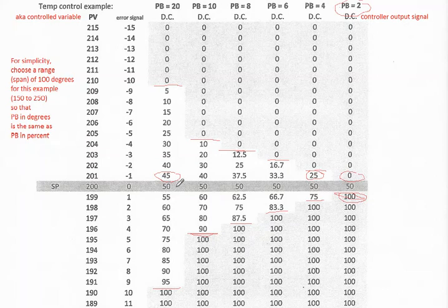We did talk about having that as another topic. You would need some flexibility there to make sure that the controller output signal matches what it would take to maintain, in this case, the 200 degrees. A lot of that comes down to sizing your system, the actual sizing of the heating elements to the system itself. You wouldn't want to oversize or undersize the actual heating element. So those are other topics too. Maybe we'll get to them in the future.